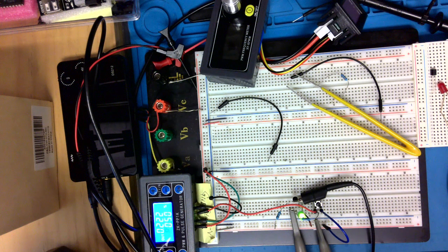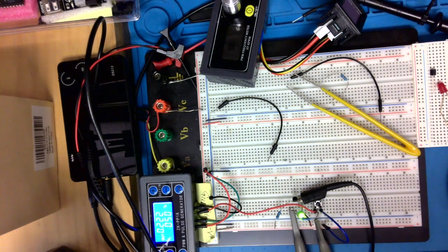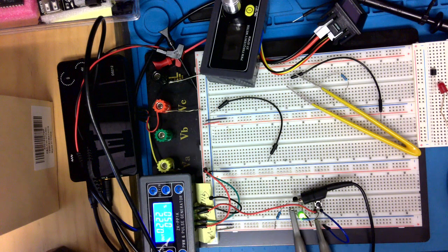So what happens is they attach a Schottky diode from base to collector. The Schottky diode's on voltage is very low, like 200 millivolts. So the collector is clamped to 200 millivolts below the base, so the transistor never saturates. It doesn't go all the way into saturation, only slightly saturates. So turn-off speed improved dramatically, and that is called the Schottky transistor.